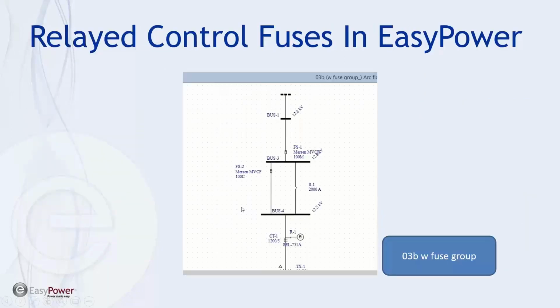Well, currently in EasyPower is the ability to do swapping of a fuse based upon a switch being in parallel with the current limiting fuse, or a lower rated fuse, such that once we detect a fault, you open the switch and it forces the current through the more sensitive fuse. And again, this is something already in the system.